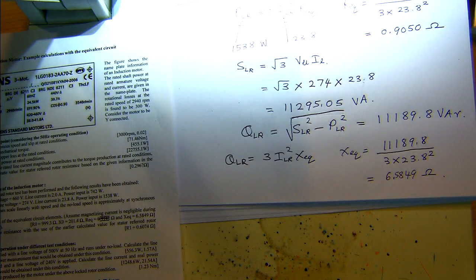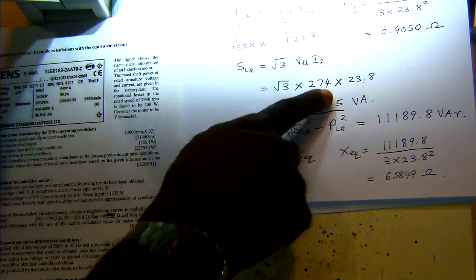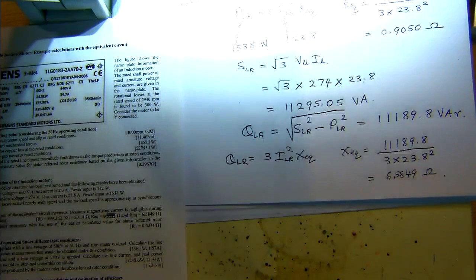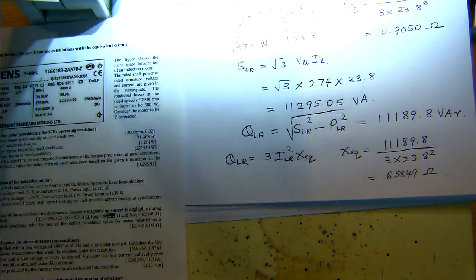One of the mistakes that we've seen is that you mess up the equations in terms of per phase power if you are given the total power. So let's say in this example you are given the total real power, but then when you are calculating you need to have the 3 times this, otherwise you'll have a √3 times difference in the resistance.